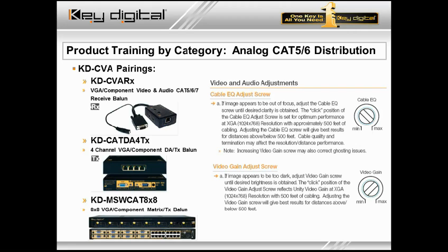And once you maintain that proper video gain setting, you proceed to your cable equalization screw as we discussed here. Without the proper cable equalization, you may see some artifacts on the screen.